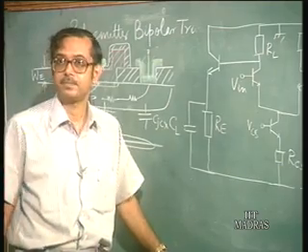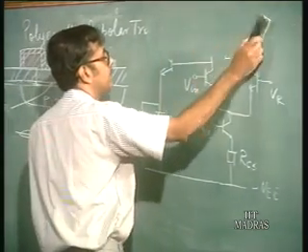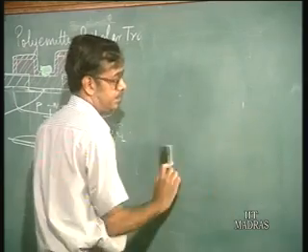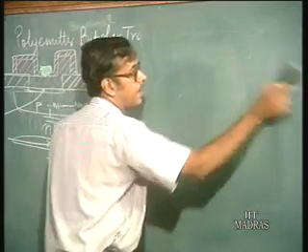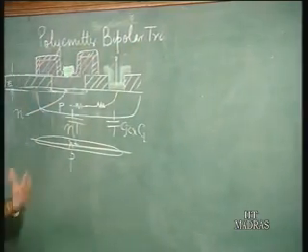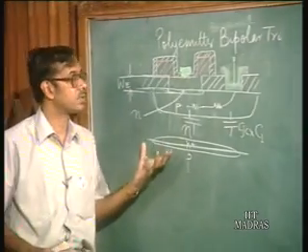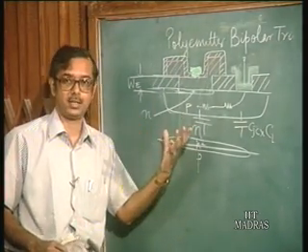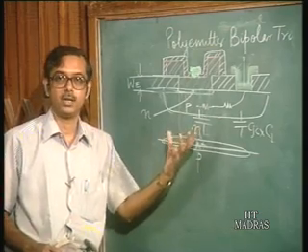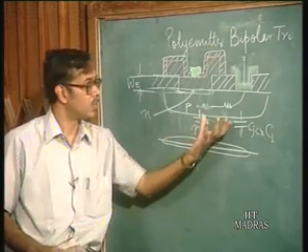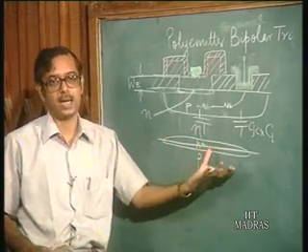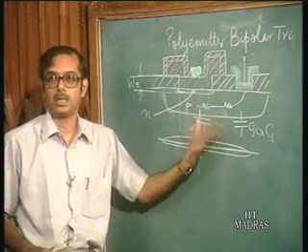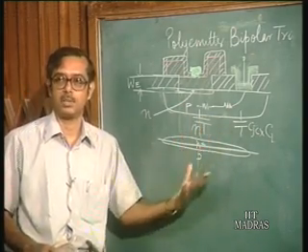Again, what is done is you have what is called a self-aligned structure. You must have a self-aligned structure to reduce the values of the parasitic components, all the parasitic components, that is, which are not actually taking part in transistor operation, for example the extrinsic components, but which have an effect on the performance.